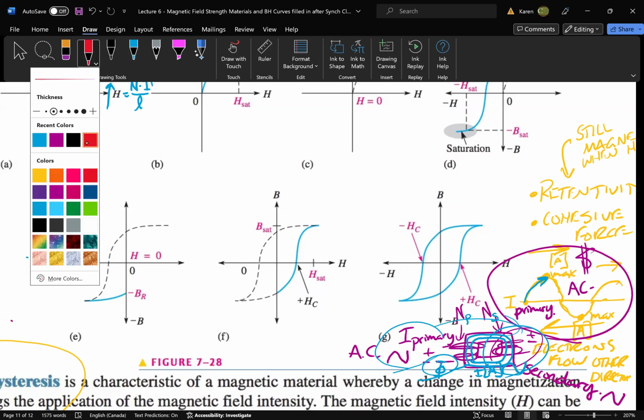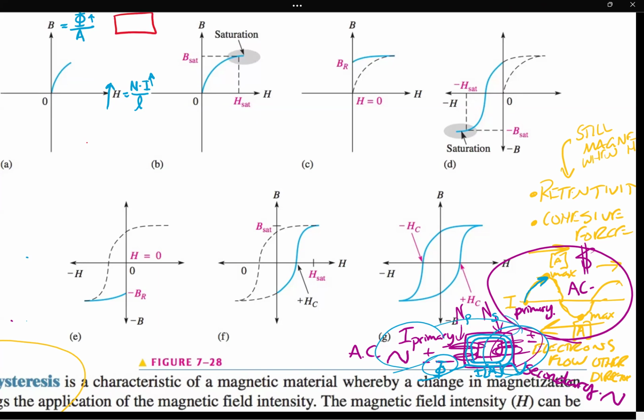Well, what's actually happening is that I am going from a material with all of these north-souths misaligned to all of the north-souths being aligned, and this is magnetic saturation. Well, this is a physical process to align all of these into their boundaries, yes? And physical processes don't just turn on and off. This has a gradient and it has a lag. So I want you to remember it is a lag.